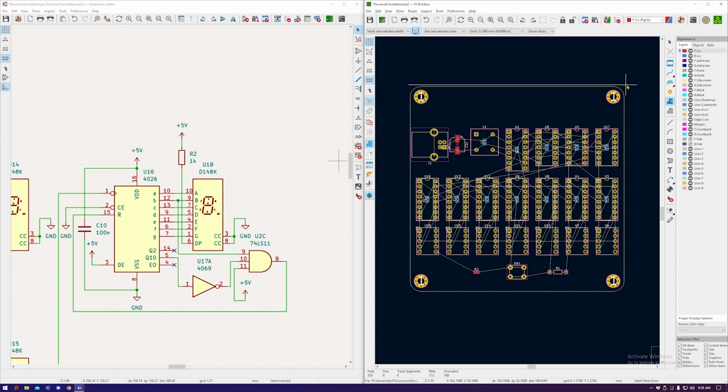I don't have hundreds of layers, so I can't make a different layer for each voltage. Also, ground on both sides, especially if you add via stitching, is a lot better for noise rejection, and it's a bit like shielding around your circuitry. But for this we don't care, and on most boards it's better to just have power so we can minimise the number of traces we need.